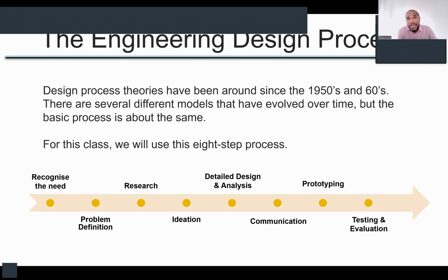And we identified the 8-step design process that we would use in this class. And we ran through them last week. We say you begin by recognizing the need, then you do problem definition, then you research, you ideate, you do detailed design and analysis, then you communicate your design idea, and then you create a physical prototype before you now run testing and evaluation. So we will run through these stage by stage and discuss.